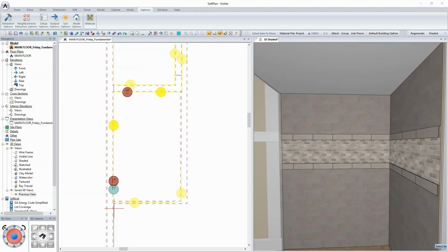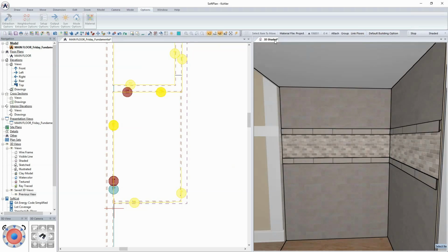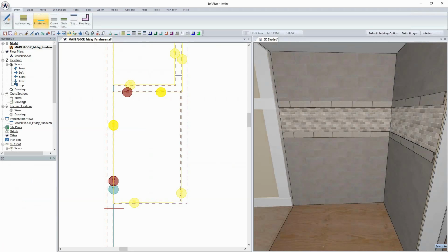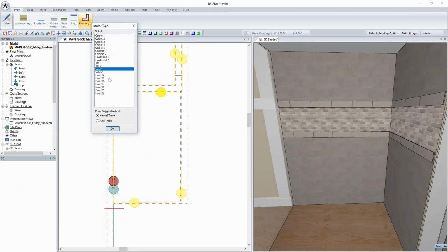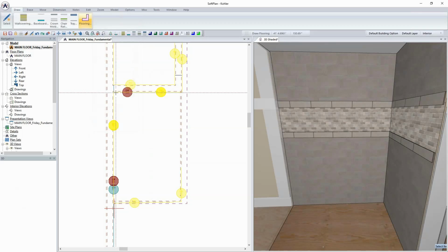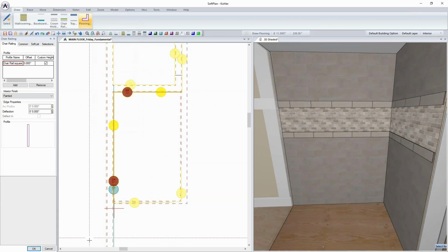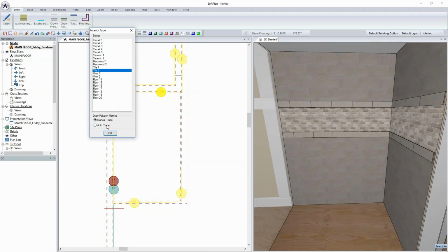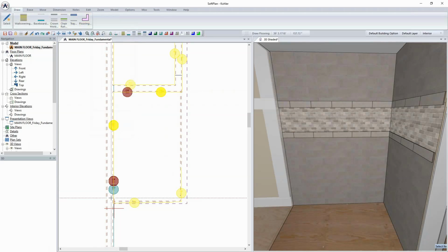Now, as far as the floor is concerned, which I've got down here, I'm just going to place a floor in there. So I may come in through the drawing here and simply through flooring, you can pick what you're going to do as far as the tile is concerned. I'm just going to use the defaults that are here, tile number 2, and I'll simply manually trace where I want this tile to be placed. So I'll click on my flooring, I'm going to manually trace my tile, and then I'll just click and sketch where I want this to go.